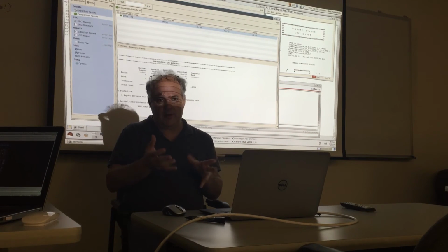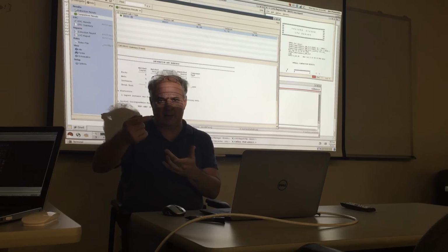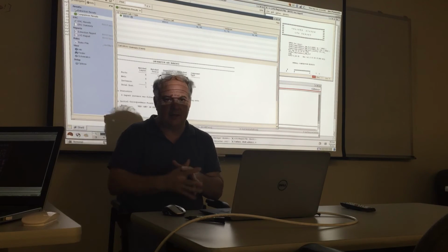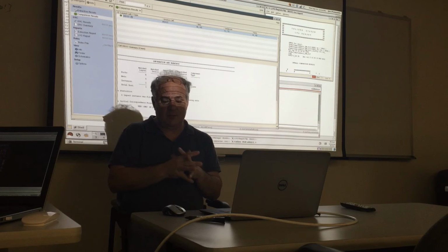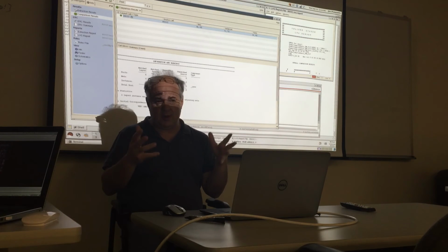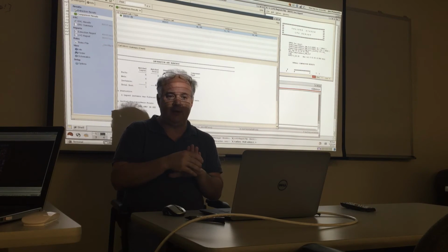Common things are, if you forgot to tie the bulks down in the schematic, that'll give you a violation. It's usually pretty good at telling you where the problems are. You can go there directly and fix them. Sometimes, as I said, when you do something like a D flip-flop, things get more complicated and a little hairier.